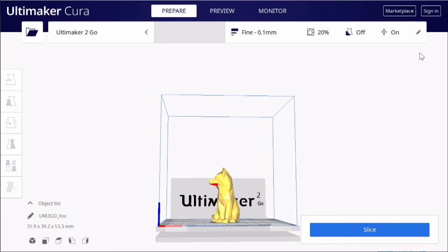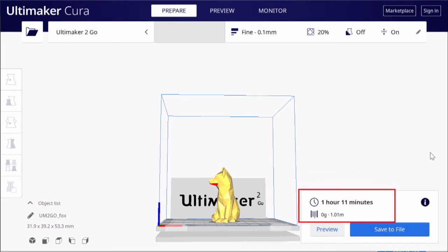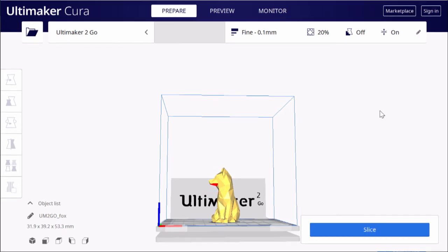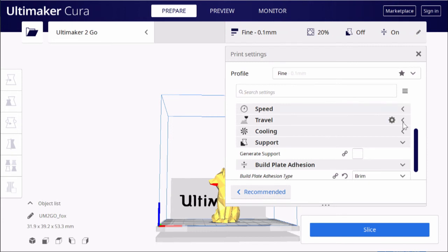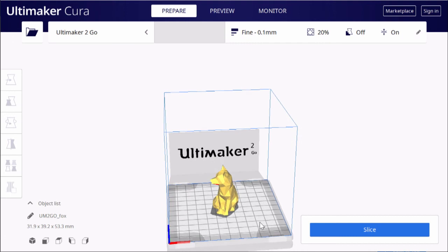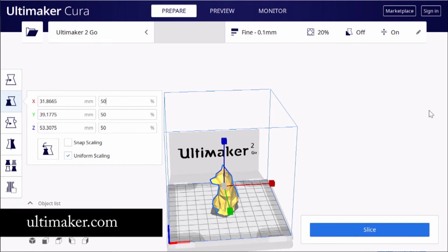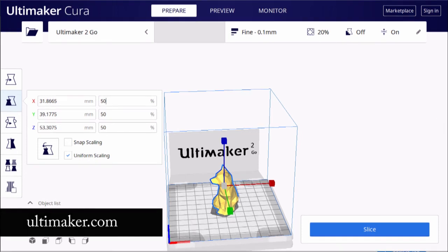Once we receive your file, we'll use the software Cura to create a file readable by the printer. The Cura software allows you to preview print time and estimated material. You can also add supports to objects that may have parts that stick out and may droop during printing. While this is not required to submit your file to the library, the software is free to download to your computer if you'd like to try it out.